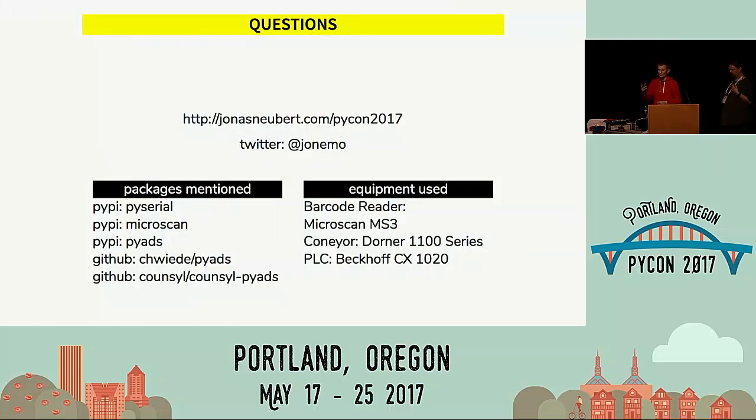Well, I actually skimmed over the part where most factories usually have these serial to Ethernet converters scattered around, and that's true. You would obviously be using that, even though sometimes those can be hard to communicate with. Devil's in the detail there. One place I worked at, actually the folks at Council who contributed that PyADS library, our approach there was to use XML-RPC servers just as this boundary, one team works up to the XML-RPC server and then other teams have a unified interface to every device, and that's how we did it there. But again, there are like hundreds of manufacturers with like thousands of devices, so it really depends on the case. Thank you.